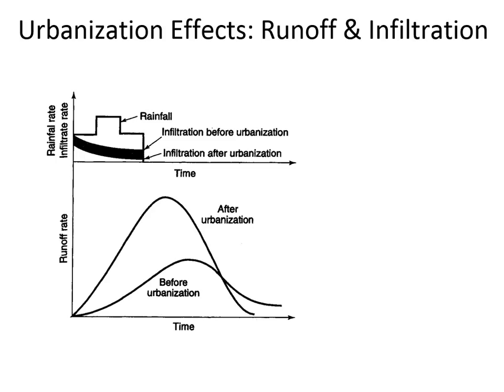Now, the other thing to take note of here is that there's this curved line, and that curved line is the infiltration rate. At the beginning of the storm, the soil is infiltrating water very quickly. It has a high infiltration rate, but then the infiltration rate decreases as the storm goes on, because as the soil voids fill up with water, they're not quite sucking down the water at the same rate as they did at the beginning of the storm.